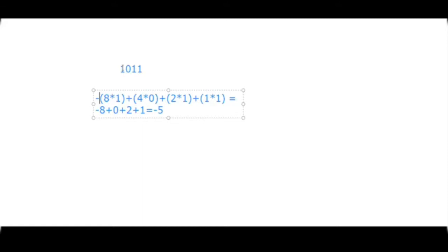If it's 1, it's a negative sign. You have to remember that. So we put the negative sign here. If 0 is there, we would not put a negative sign in a 2's complement number. Since 1 was there, it implies that it's a negative number, and the first position also has a value. Not like in sign magnitude. In sign magnitude, the first position only indicates the sign. It doesn't have a value.